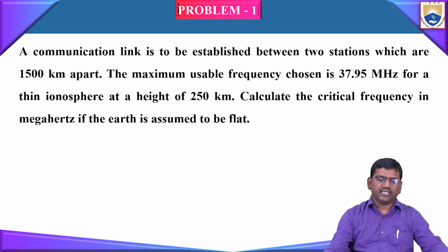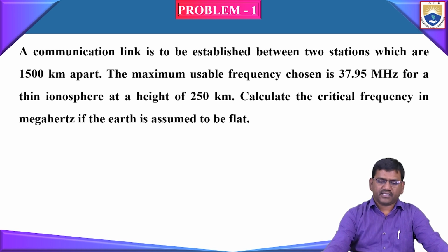A communication link is to be established between two stations which are 1500 kilometers apart. The maximum usable frequency chosen is 37.95 MHz for a thin ionosphere at a height of 250 kilometers. Calculate the critical frequency in megahertz if the Earth is assumed to be flat here.